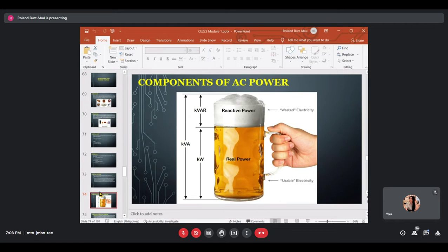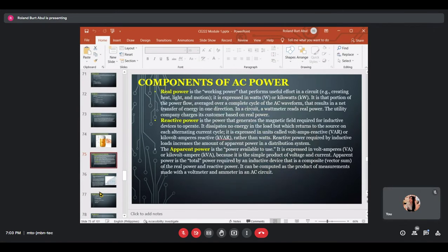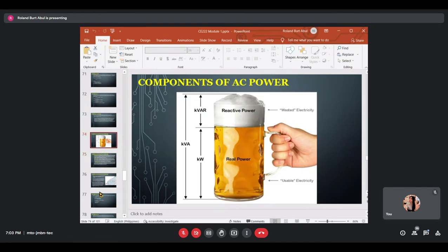So the current in the 100 watts lamp is equal to 120 over 121 ohms, which equals 0.992 amps. For the 75 watts lamp, we have 161 ohms of impedance. So the current is equal to 120 volts divided by 161 ohms, which is equivalent to 0.745 amps. And lastly, for the 40 watts lamp, we have 300 ohms of impedance. So the current is equal to 120 volts divided by 300 ohms, or equivalent to 0.4 amps.